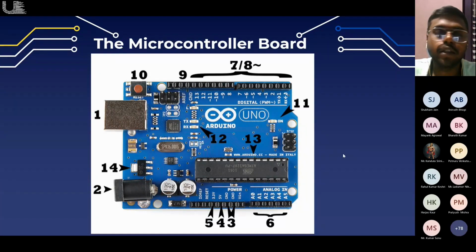Number 10 is the reset button. The reset button will temporarily connect the reset pin to the ground and restart any code that is loaded on the Arduino. This can be very useful if your code doesn't repeat, but you want to test it multiple times. When the code repeats and when it doesn't, I will explain in the further part of the workshop.